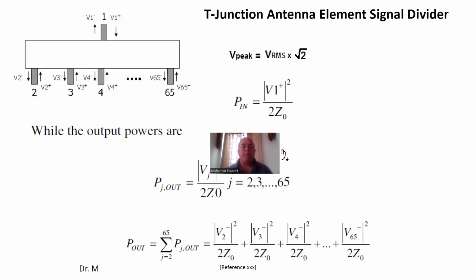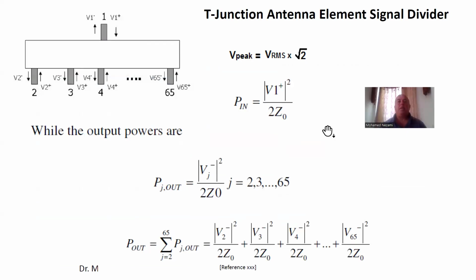All right, so let's define the antenna array feed network efficiency. The efficiency is basically you calculate the entire output power from the final dividers that feed the antennas, and divide that by the input power. You get a ratio, power out versus power in. Ideally that should be 100% efficiency, but it's not. There are losses from radiation, from ohmic losses, and also reflection losses.